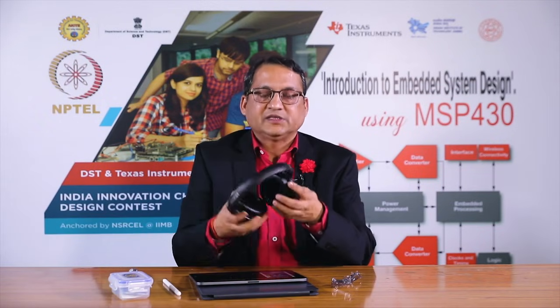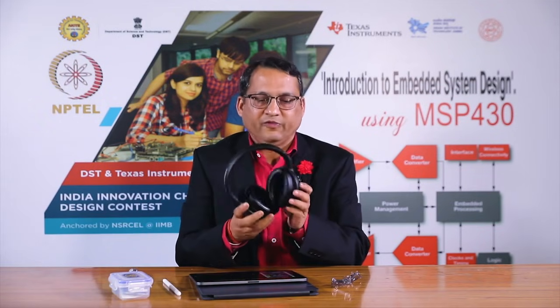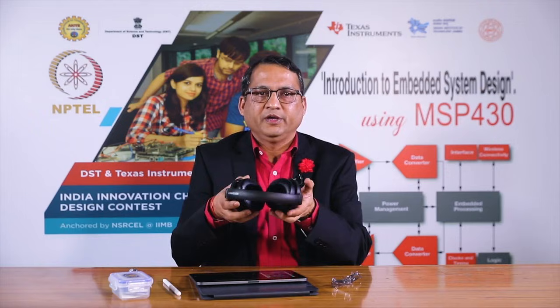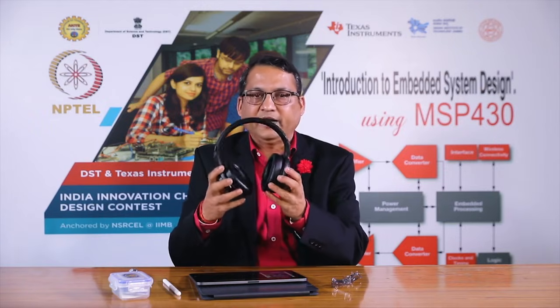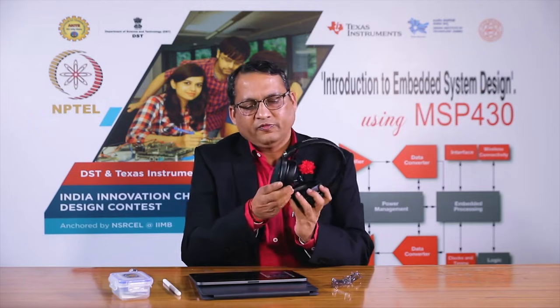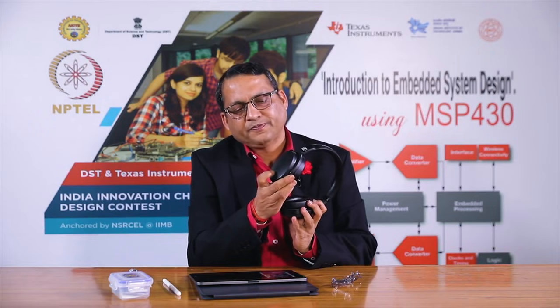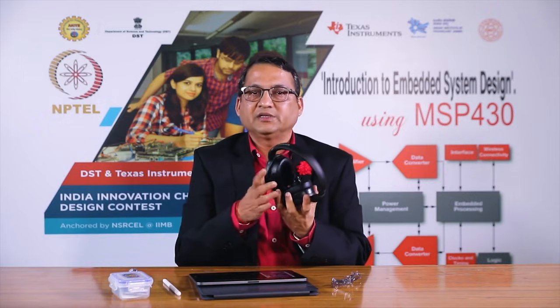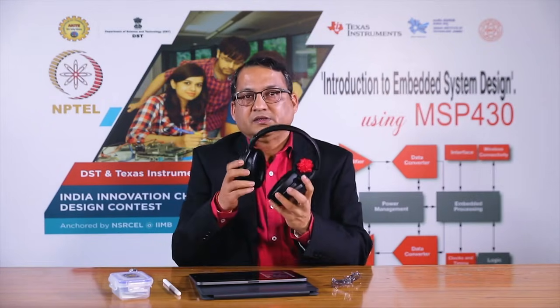The second example is this. I have these Sennheiser noise cancelling headphones. Normal headphones are mere headphones, but this one requires a battery for operation. Also, on one of the cups, there is a little hole, which is basically there because there is a microphone inside. What this does is it samples external sound, that sound which is also leaking through the cups of the headphone and entering your ears. This noise cancelling headphone samples that sound,